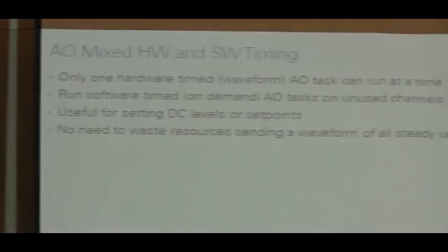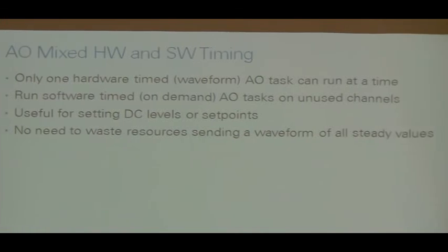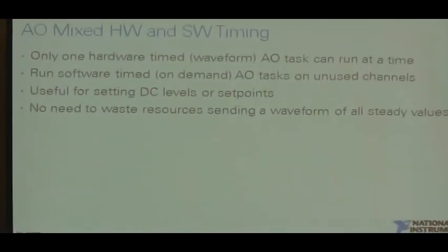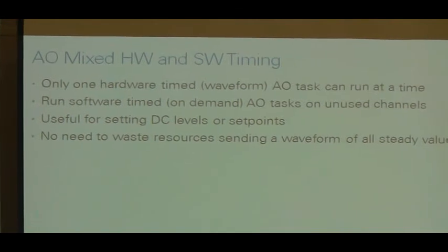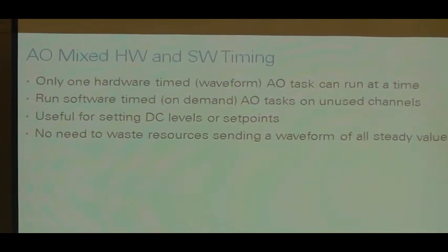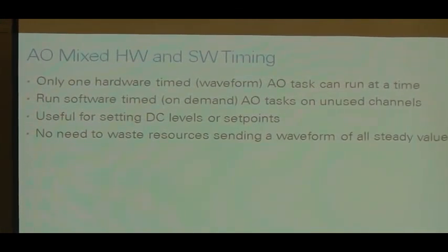So the last feature that we'll use in conjunction with this is that I can actually mix hardware timing and software timing for analog output. On a given device, you can only have one hardware timed or one clocked analog output task running at a time. You can choose what channels are in that task, but you can't have two separate clocked AO tasks running at the same time. There's only one analog output timing engine to drive them.